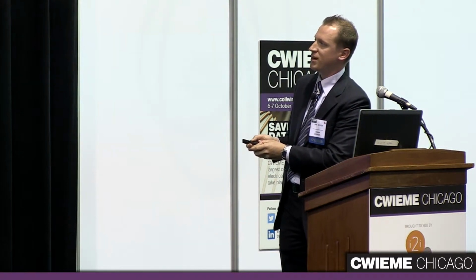So let's do that and actually look at this advanced kind of PI controller. First of all, this is the standard that everybody uses in millions of applications, and we have to add two little things. The first is we have to add this two-dimensional function of the flux linkage, which is a lookup table, and we use that to adjust our control parameters. The second thing we have to do is precisely decouple and therefore do a flux linkage prediction. So we have to take care of these two things, and then we are done. Okay, so how can we adjust the control parameters?